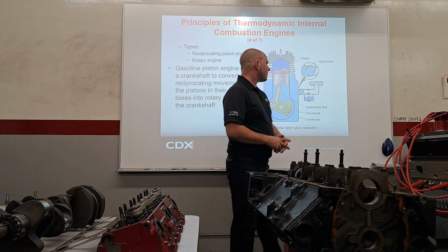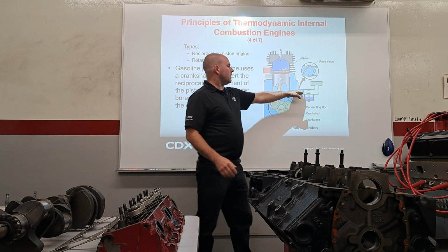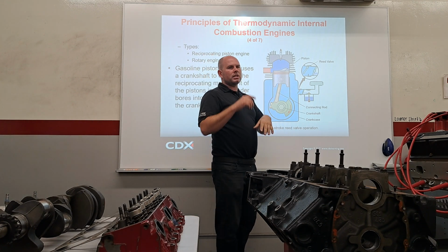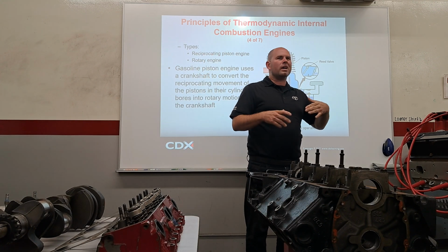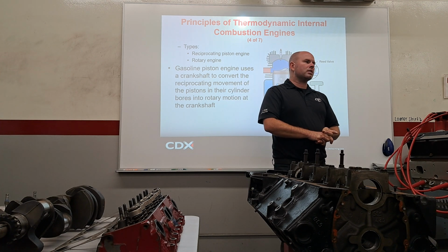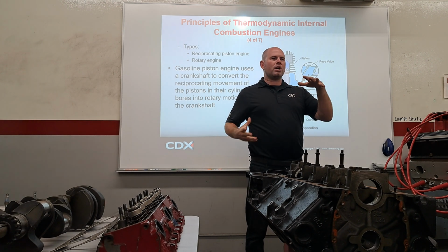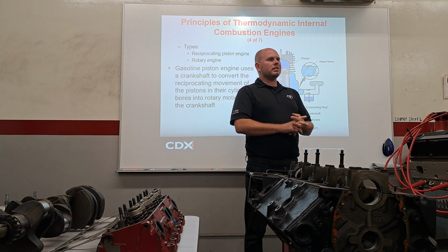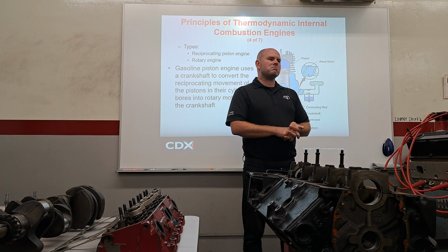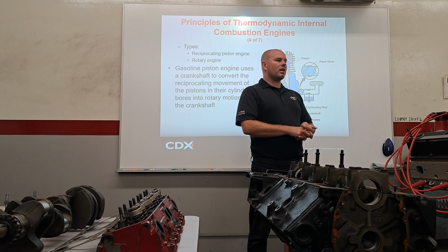So essentially, what we're going to do is get air and fuel into that sucker. We're going to compress it, because when we compress it, we heat it, and that makes it ready to burn. It's actually kind of hard to burn if you don't compress it. With a spark plug, you definitely won't get it to burn if you don't compress that air and fuel to at least close to 100 psi. You ain't going to catch it on fire. That's not to say you couldn't maybe catch something on fire if you had a big old blowtorch and that type of stuff.